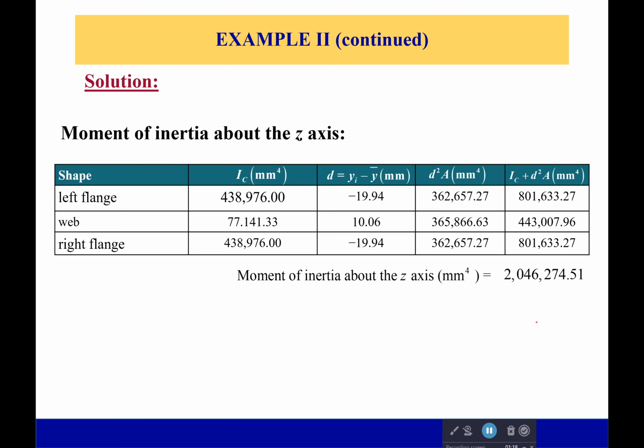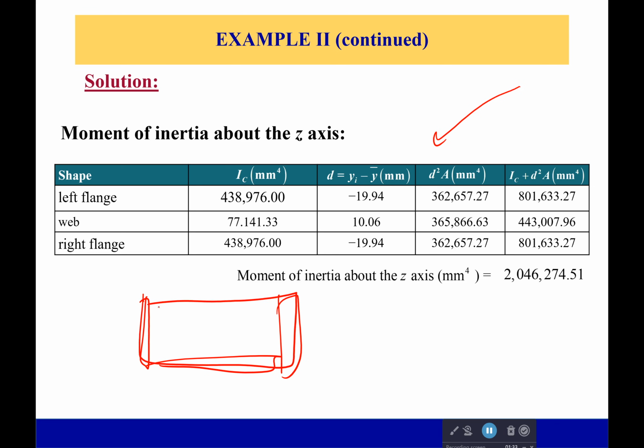Also, moment of inertia. Well, there's 3 sections, the left, the bottom, and the right. But I think this is actually a terrible way of having done this. The much simpler method would have been to simply say that there is a big rectangle and then a negative rectangle. I would have preferred to do it that way. That's only 2 sections and it would make it a lot simpler. But you do it how you know it. You don't have to do it my way. You can always do it your way.